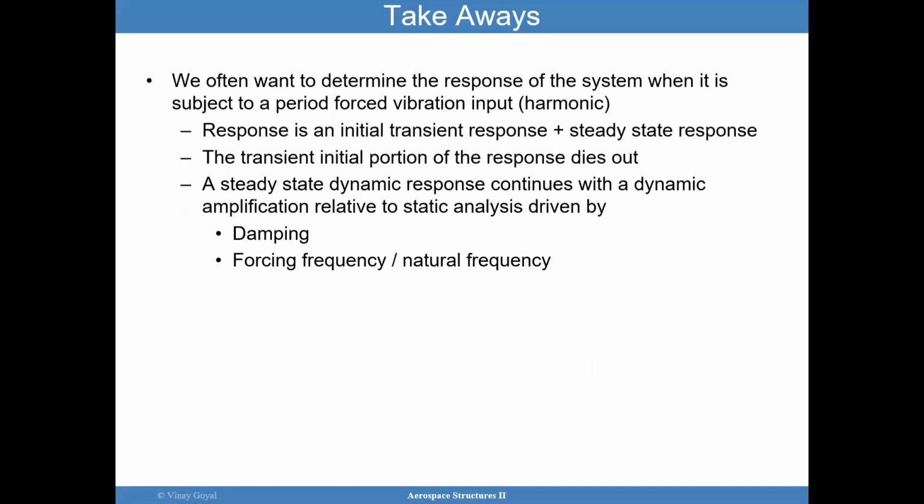So another takeaway is that we often want to determine the response of the system when it's subjected to periodic force input or harmonic input. And the response of the structure is really an initial transient response plus a steady state response. The initial transient response dies out while the steady state response continues.